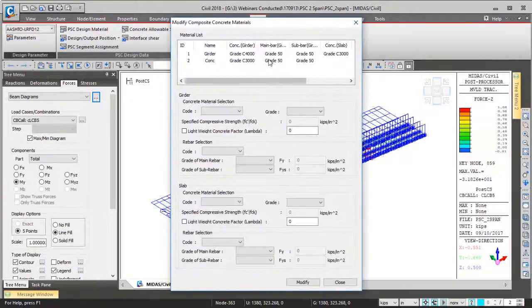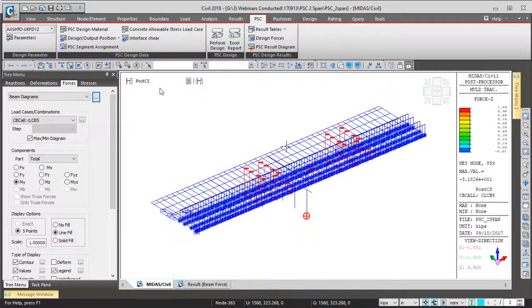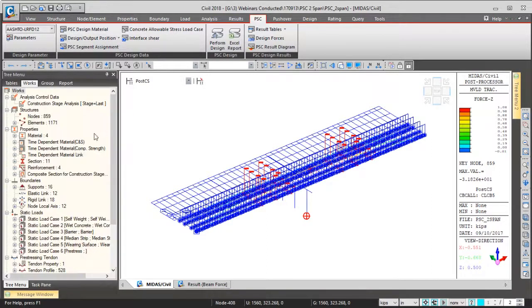Then you select the material, so the grade of your concrete girder, the rebar for that. Similarly, grade of material for your slab and rebar for that. Now, for a bridge with these many girder elements, so you can say around 100 girder elements, there would be two sections, I and J. So overall, there would be 200 locations where you would be getting a design.